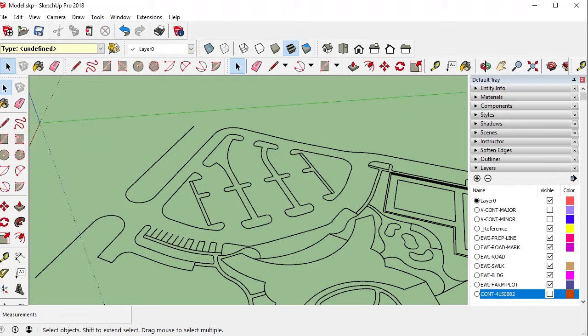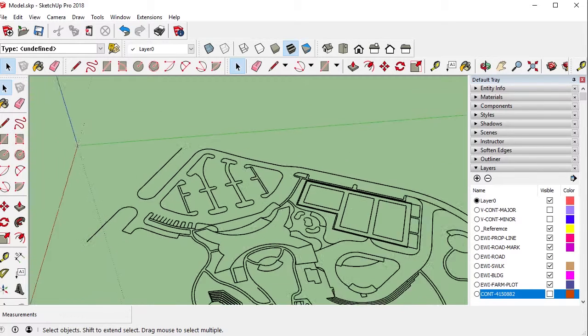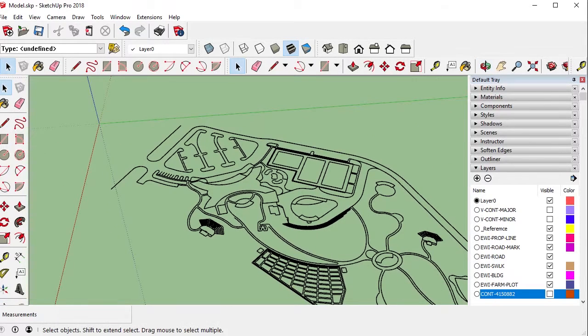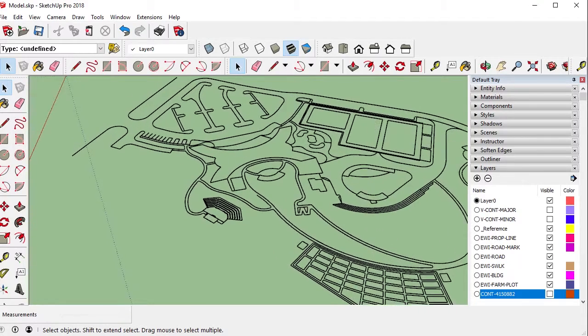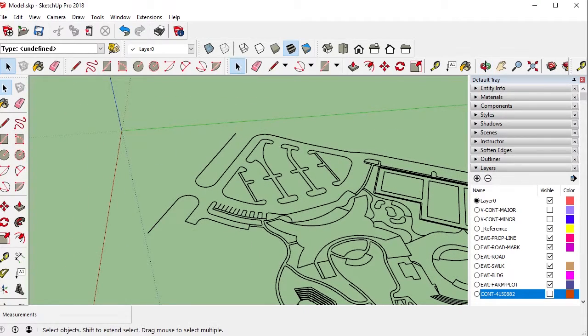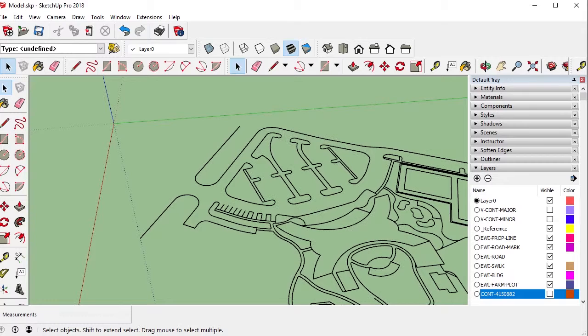Like I said, I normally like to take line work, maybe just only the parking lot, only the pathways, only something else, so I can start determining which may actually not work when we start draping. These lines here have no resolution. There's nothing that's going to get closed by these, so these really will make no impact on the surface other than probably making it more complicated. We actually want to make sure all of our surfaces are closed.